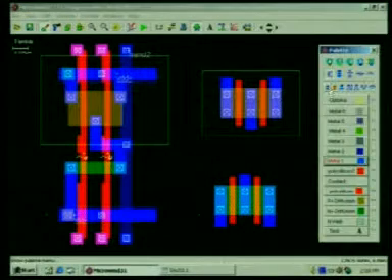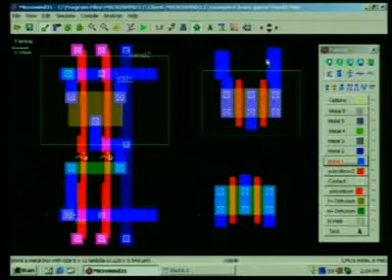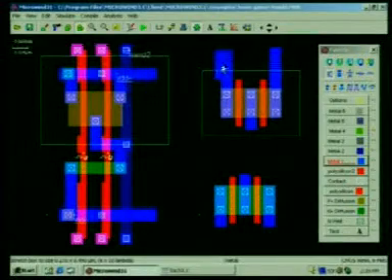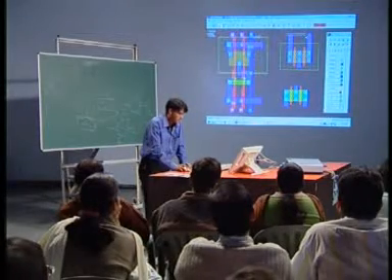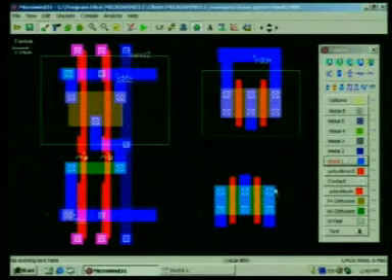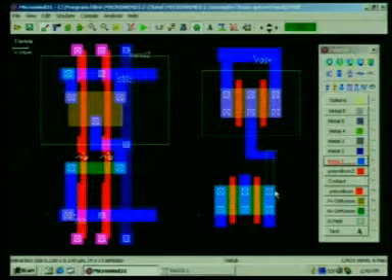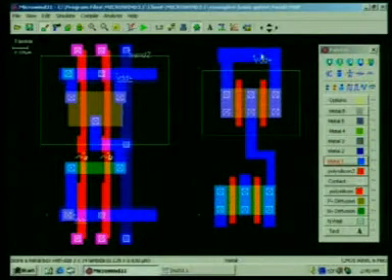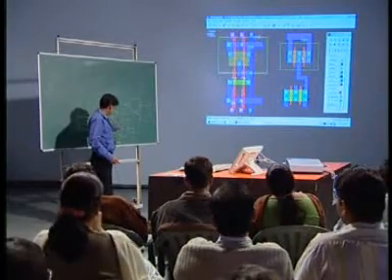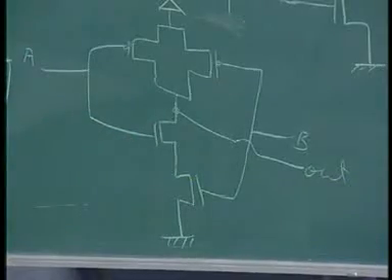One simple way is to just increase this metal and this one, like this, and apply the VDD here, and now you need to connect this one here. So, just extend this one like this. I am just redrawing that circuit, I made these common, and at this common region I have applied VDD, here I have taken the common connection. After that I have connected to the source of this simple NMOS.